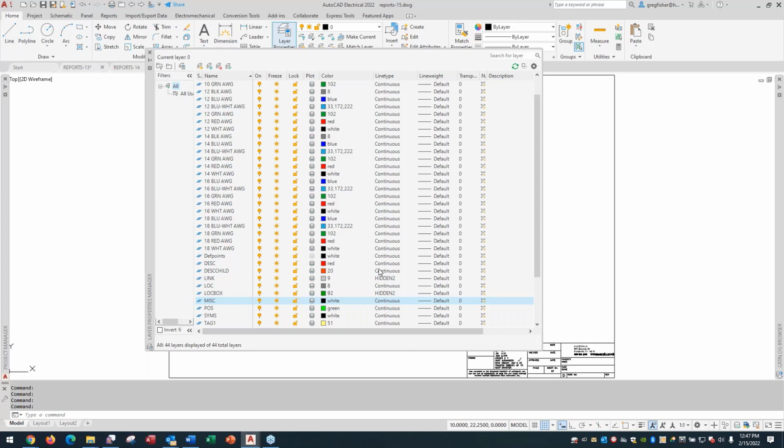You can also create a new layer. Maybe you want to reserve that miscellaneous layer. Create a new layer, the regular AutoCAD way, called reports. We can create our own layers all day long inside the software. And then after you insert it, just move it to a different layer. But that's another thing that you can run into.